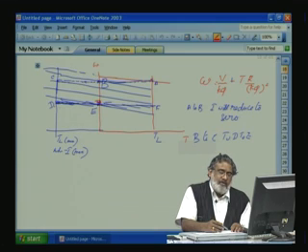So, the moment the motor comes to the correct speed, we will adjust the voltage such that we slowly increase the applied voltage, so that the negative torque, the current, will slowly reduce. So, it will go along many parallel lines in a horizontal way here, and it comes to 0 here. These depend on the electrical time constant, but C to D is a slow process that depends on the mechanical time constant; the machine is slowly decelerating. Again we apply voltage such that the motor should not slow down, we have to apply a positive torque. So, the motor will slowly come to this position.